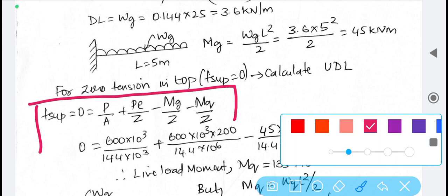See, the major change here is that this expression is quite different from the expression used for the simply supported condition. Since the load value is also unknown, we cannot directly compute the compressive stress, and thereby we make use of the fundamental concept of pre-stressed concrete.